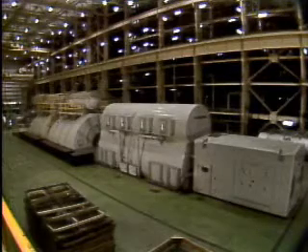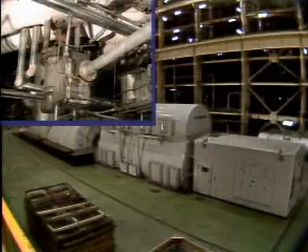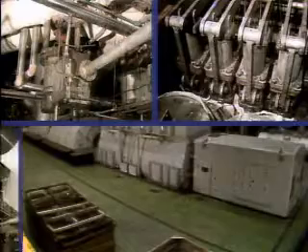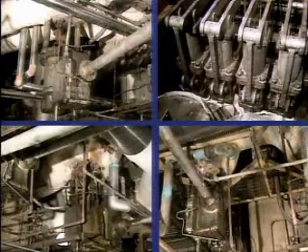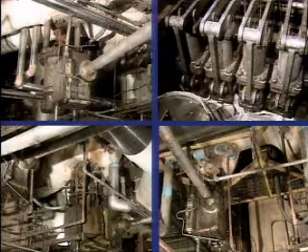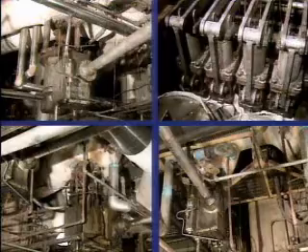When the turbine trips, all four types of valves, the stop valves, the control valves, the reheat stop valves, and the intercept valves, quickly close, cutting off all steam to the unit. A trip protects the turbine from danger by immediately shutting off steam flow to it.